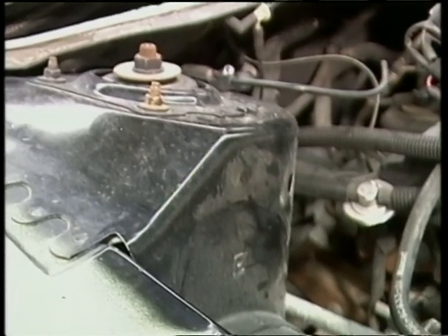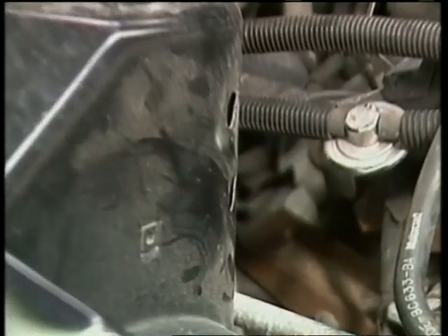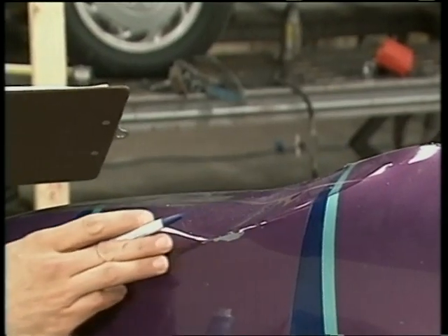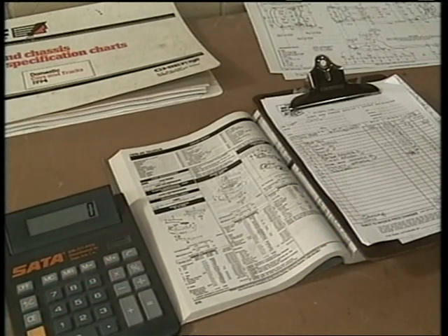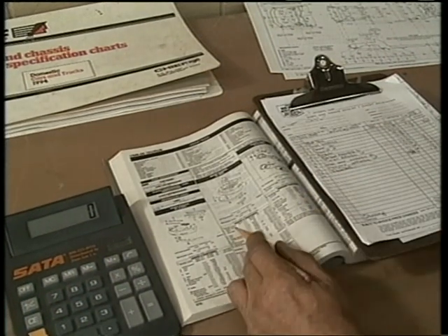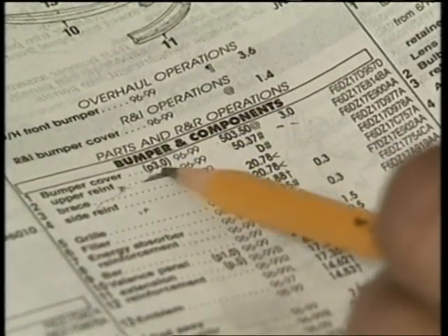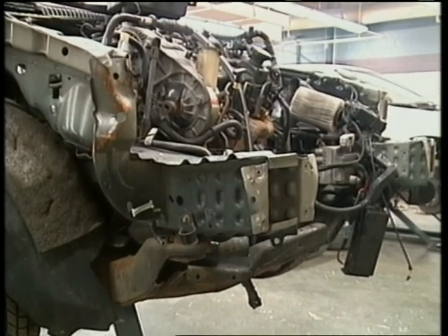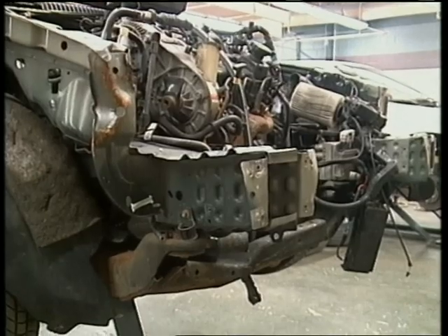First, if damage is located near a stress area, such as an engine or steering mount, then replacement is required. If the metal is kinked or tightly folded rather than bent or dented, then replace it. If the time cost needed to make a repair exceeds the cost of a replacement, here again, replace it. If the damage is located directly within a crush zone, then again replacement is required.